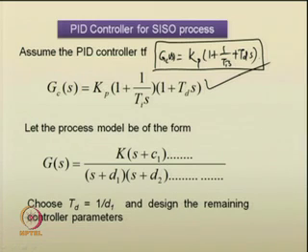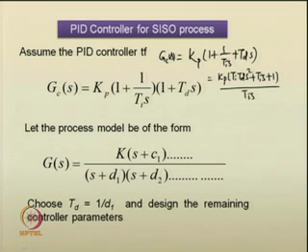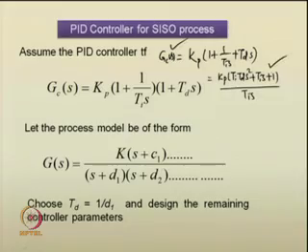If you simplify this, it gives us an expression in the form of Kp (Ti Td s square plus Ti s plus 1) upon Ti s. So, from this expression we say that the transfer function of the PID controller in parallel form introduces two zeros in the closed loop system and one pole at the origin.